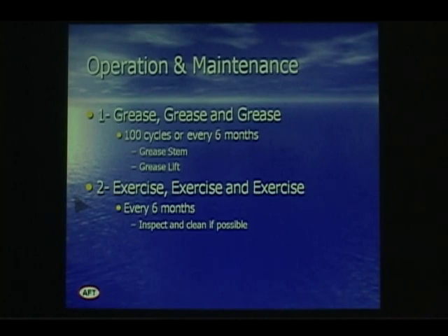In terms of maintenance, really two key things. One is to grease it and one is to exercise it. What we like to see is every 6 months or 100 cycles, depending on the frequency, is to grease the stem, grease the lift.